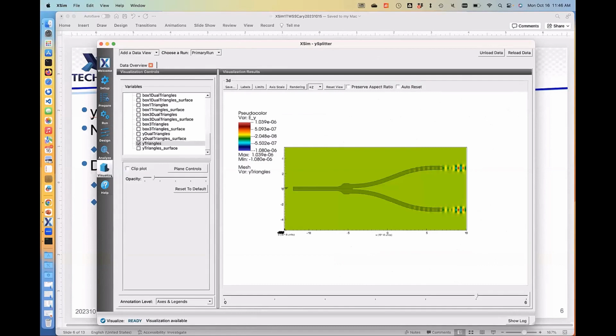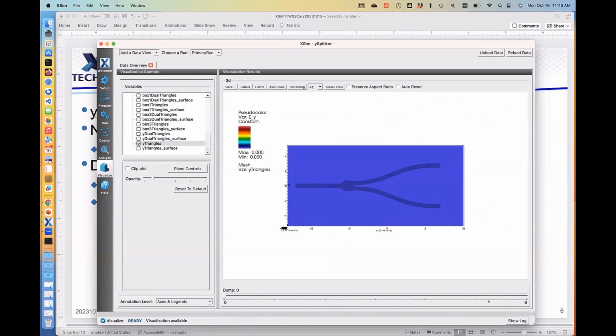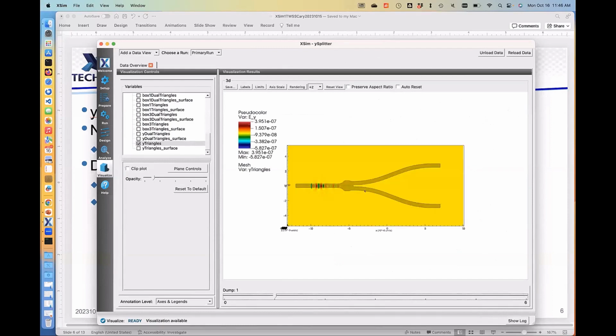And finally, visualization. So for this particular simulation, it starts off quiescent. And then at the first time step, there is a mode, and it's being launched right here at this -10 number. And this is one of the things we really like about this, this is called a unidirectional launcher. And what that allows is you, for the largest part, to launch your electromagnetic radiation in only one direction, because the radiation that goes backwards is of no help. And in fact, it hurts you because it reflects off the boundaries of the simulation and can interfere with your signal analysis.